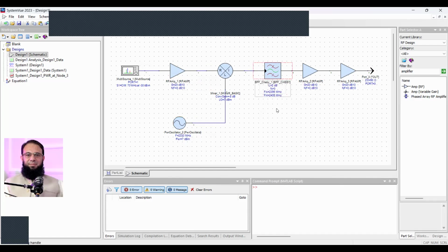And here we are putting the very narrow bandpass filter, and then the amplifier stages in order to get it over here. So if you note, over here it is minus 30, and here minus 30 is brought to a high power level by this amplifier, but then there is a conversion loss over here. So this loss, and then the loss of the filter, and then again the amplification made us able to get a 20 dBm output power.